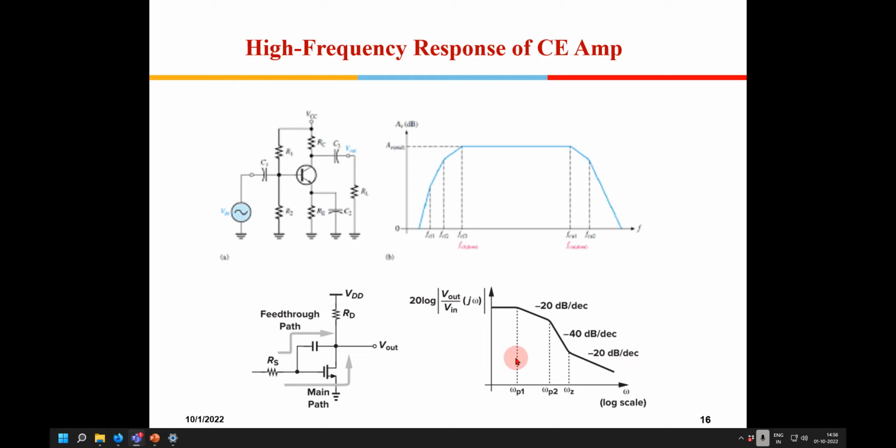Okay, this can be 20 dB in case there is a zero which is coming onto the numerator, so it can offset this minus 20. It can have a plus 20 dB. So these are the two poles. If a zero comes here when you write the transfer function, then this will go to minus 20.